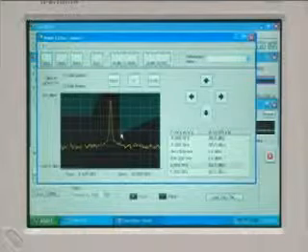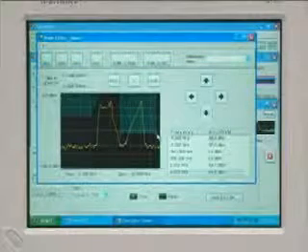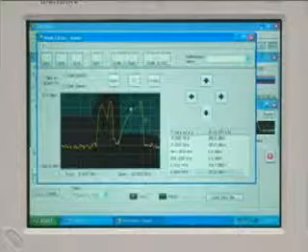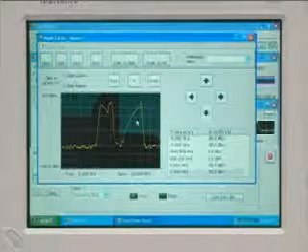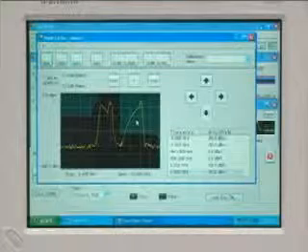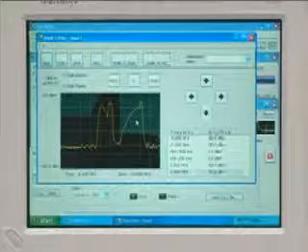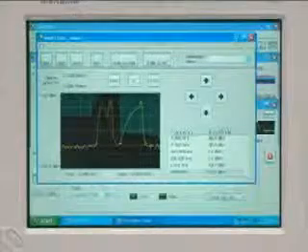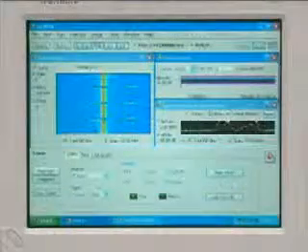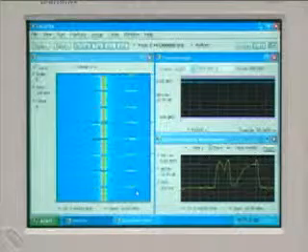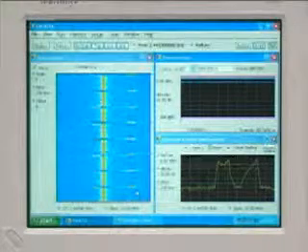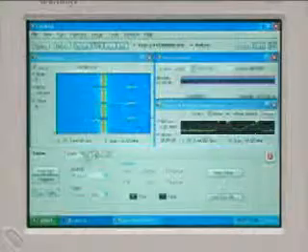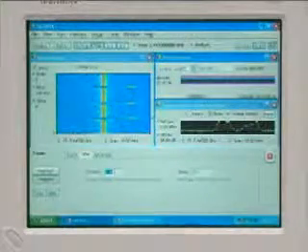By altering the default mask tailored to our signal, we can cause a trigger every time the signal violates the area we've designated. The trigger captures 900 microseconds worth of information every time the signal moves from the main carrier frequency. Now we can see how the signal moves during the hop, and with markers and the zoom feature of spectrogram, we can completely characterize this repeating but hard-to-find hop. We can find out the settling time and how long it dwells at its other frequency before returning back.